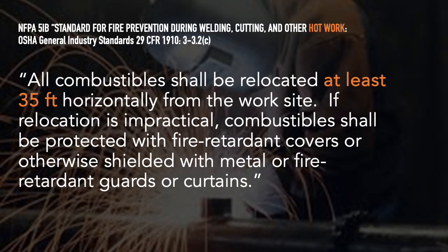So this is NFPA 51B, Standard for Fire Prevention During Welding, Cutting, and Other Hot Work. It is also OSHA's 29 CFR 1910.252. There's a standard for trying to prevent or remove flammable sources. All combustibles shall be relocated at least 35 feet horizontally from the work site. If relocation is impractical, combustibles shall be protected with fire retardant covers or otherwise shielded with metal or fire retardant guards or curtains.